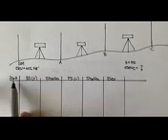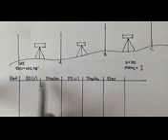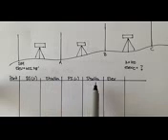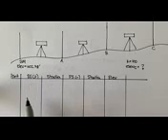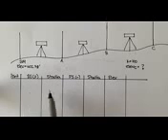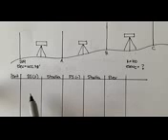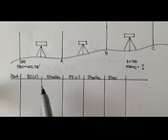So, on our little chart that I drew here, I put a column for the point, benchmark, A, B, and C, then our backsite, our stadia check for our backsite, our foresight, our stadia check for our foresight, and our final elevation. Remember, the main difference between differential leveling and three-wire leveling was that instead of taking just one reading for the backsite, now you're taking 3. And because you're taking 3, you need to check if the half stadias of those 3 measurements are in check or are roughly the same. If they are, we can move on to the next measurement.